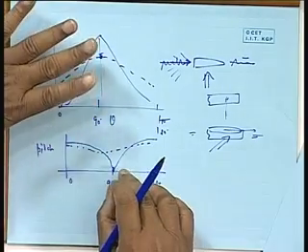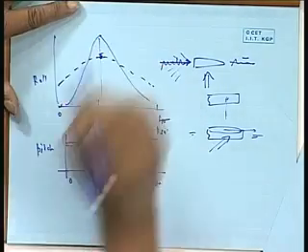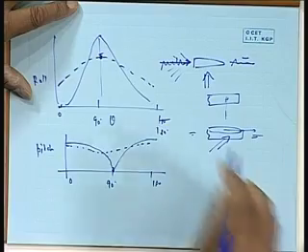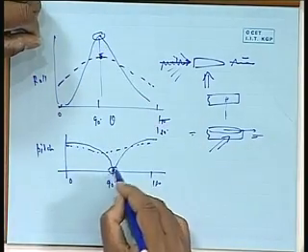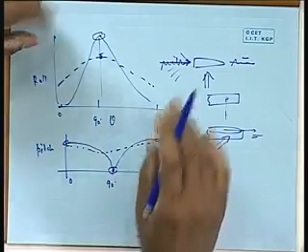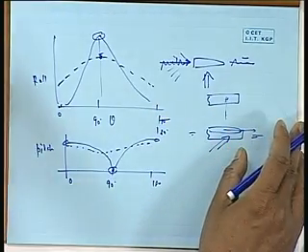Actually, the drastic difference comes in roll. But as you can see, if you want to do a conservative design, this is maximum. Again, this is maximum. I mean, this is higher. So therefore what happens in a design is that if you have designed a ship which survives in long crested waves, then you are actually designing it for a worse condition. You are on a more conservative side.